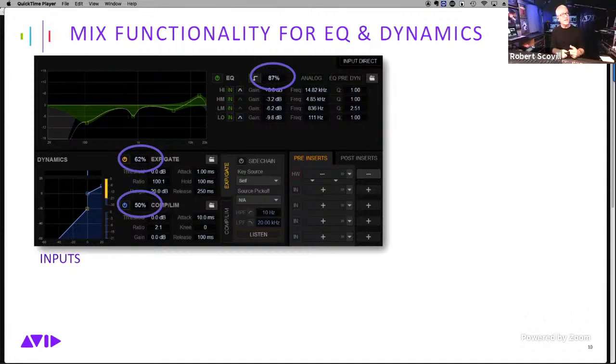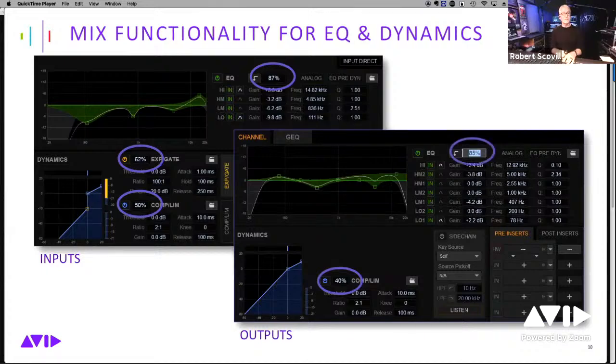As far as the equalizer, using this parallel setting for an equalizer actually kind of creates a scalar. That's what we call it, a scalar. So you could actually adjust this up and down, and it will take all of the filters in the EQ and adjust them by a given ratio. So it's just a fantastic way to work and adjust your filter sets and really dial in your tonality. As you'll see here, it really works great on outputs. If you're doing system EQ and using this scalar, man, it is fantastic for that kind of work.